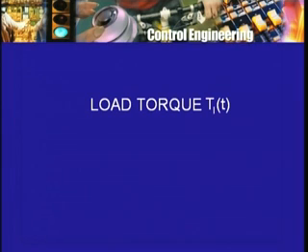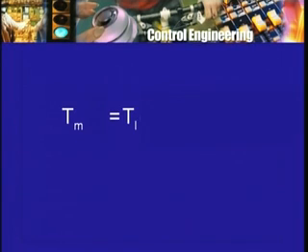Think of the grinding wheel example. The grinding wheel is mounted on the motor shaft and is pressed against some surface which is to be machined, and there is resistance to that motion. So there is a counter torque, or rather the grinding wheel must be applied a certain torque for it to rotate. The surface being machined is opposing this motion. Therefore in this sense we can talk about the load torque, and therefore Tm will be equal to TL, the load torque.